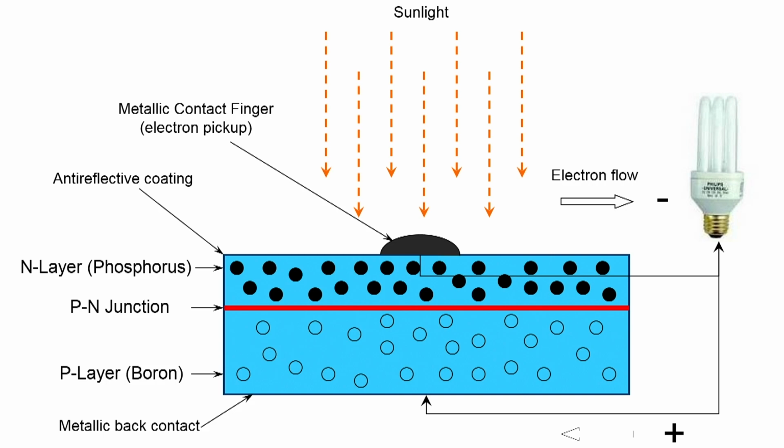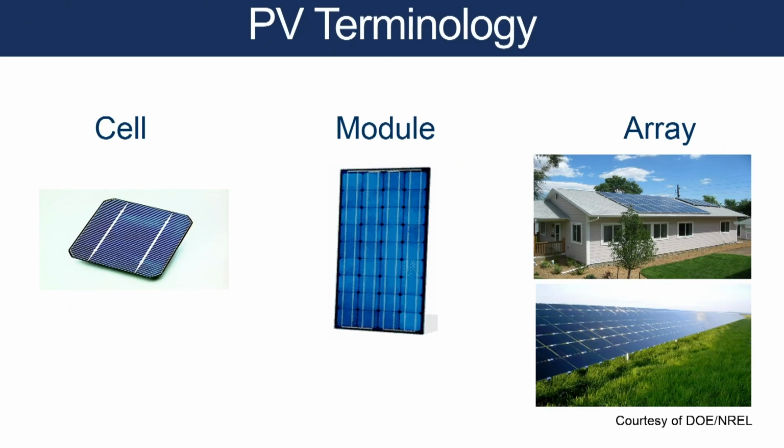and if you take that current off, that flowing electricity is what you want. Okay, so now what you do is you take this silicon and they make it in a factory and they slice it up and they make it into cells, they wire it up, and they put these cells on a backing with 72 of them or 96 of them or more, put glass on top of it, a metal frame to make it safe and long lasting, and put it on a house: cell, module, array. And you can make more, make less, it's very modular, right?